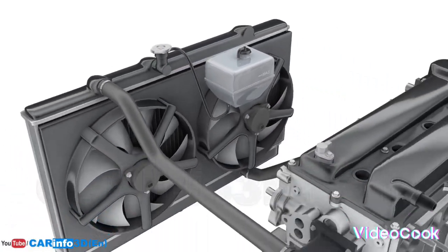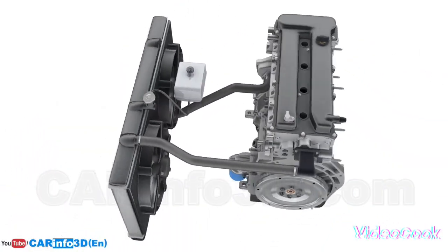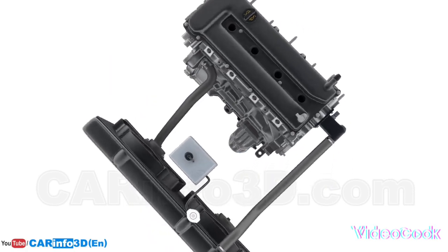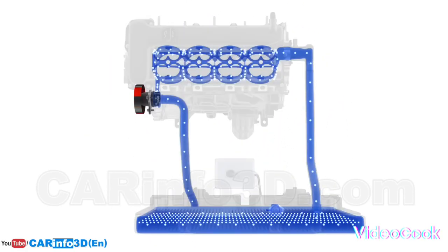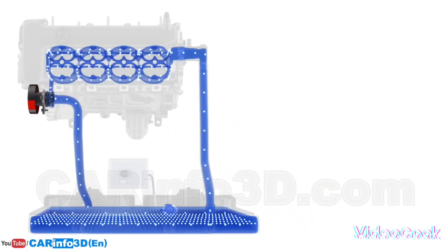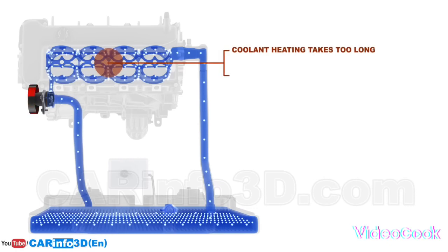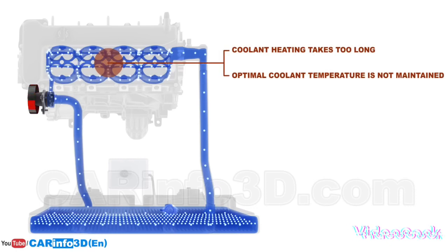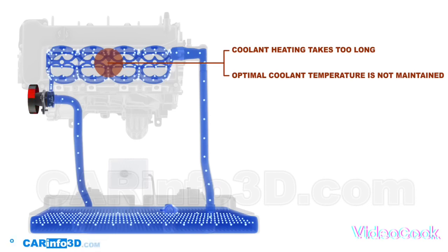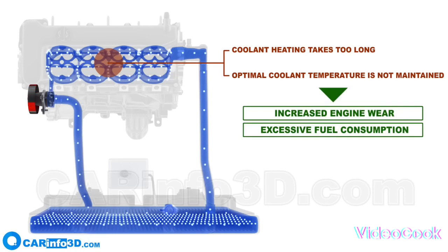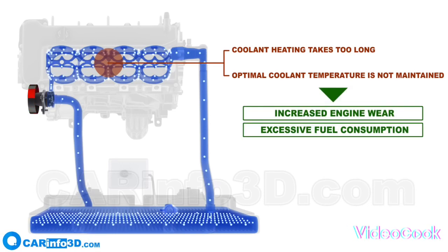This system is already capable of cooling the engine. However, due to the continuous passage through the radiator, it will take a long time to heat the coolant in this instance, and maintaining the appropriate working temperature will be a problem. This will result in increased engine wear and excessive fuel consumption.